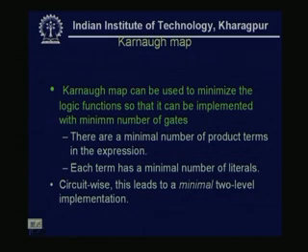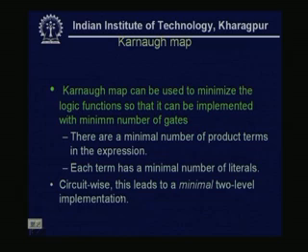And if we consider that circuit, because we have always seen that if a Boolean expression is given, some truth table is possible, and if truth tables are possible, then AND-OR realization is always possible. So, circuit wise this leads to a minimal 2-level implementation, and that is why this is very important in digital circuit design.